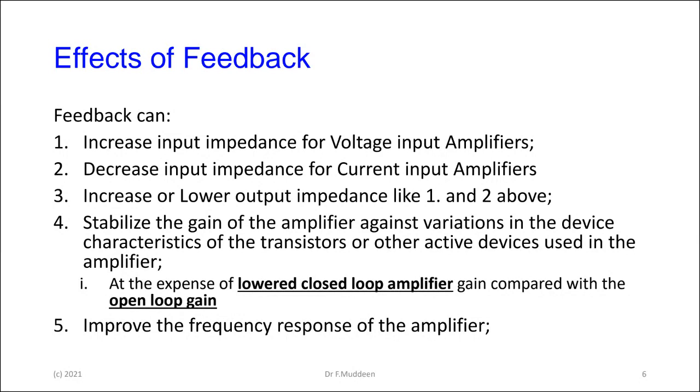On the other hand, if you have an amplifier that is taking a current as its input, you want an input impedance that is as low as possible, so it takes all of the current. The current doesn't drop across the source resistance, and you lose, because it's in parallel with that, so you lose some current through the source resistance, and less comes to the amplifier.